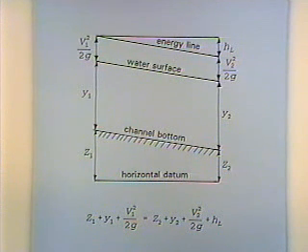And HEC-2 is a program that does the standard step method, a solution of the energy equation, for water surface profile computations. And with HEC-1, the hydrology, you get the discharge rates associated with given probabilities, and then the water surface profile computations delineate how high the water's going to get and what land's being covered.